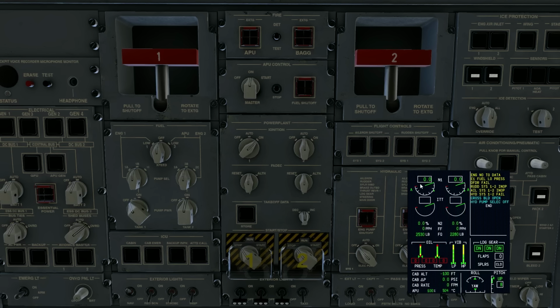You don't have to, because again, it's going to just change FADEC when it starts the next time. But you do have the ability as well during some procedures, if for example, a FADEC's misbehaving and something's not working right, you can change to the other FADEC to see if that affects it.